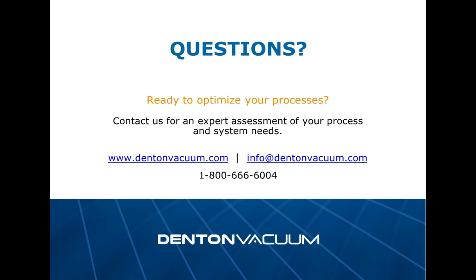Here's a question: any recommendations on cleaning before deposition or pretreatments? For example, what is a good process before IBS, ion beam sputtering, for best quality? Typically, if there is any masking involved, you would want to ash away the remaining photoresist off the surface. You would like to etch off the oxide. You can do that either with the assistance of an ion source or chemically, or both.